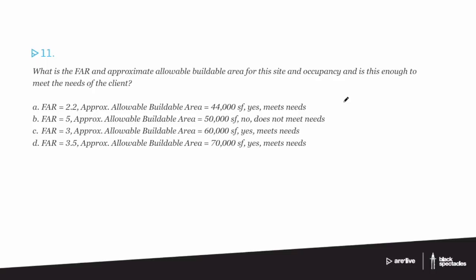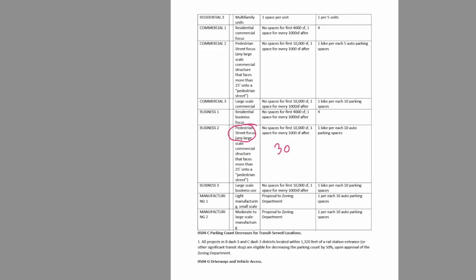So probably the first thing we're going to want to do is take a quick look at the zoning code and try to understand what we think the FAR is likely to be. So let's do that real quick. All right, so what does it say? We have floor area ratios for the B and C districts. Dash 1, 1.2, dash 1.5 is 1.5, dash 2, 2.2, dash 3. Our zoning is B3-3, so we are a dash 3. So there we are right there, 3.